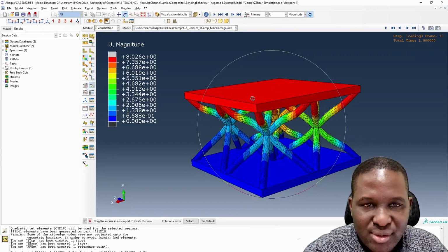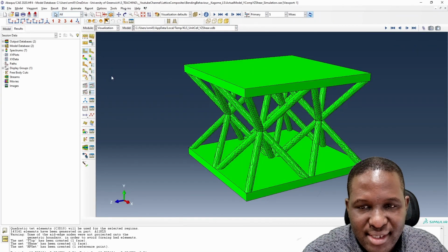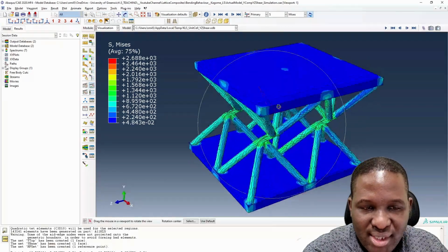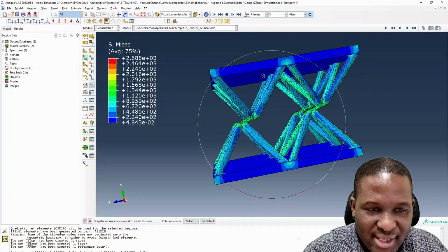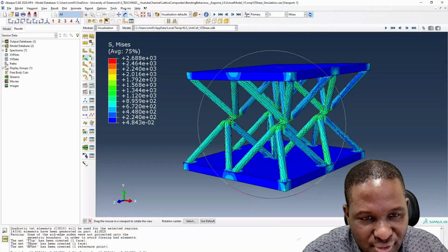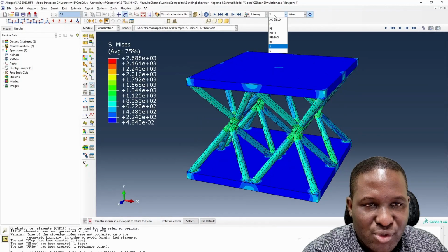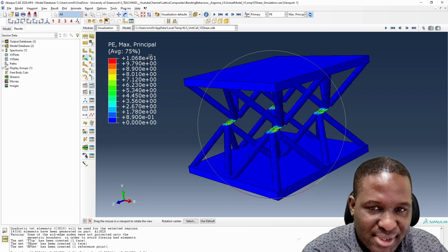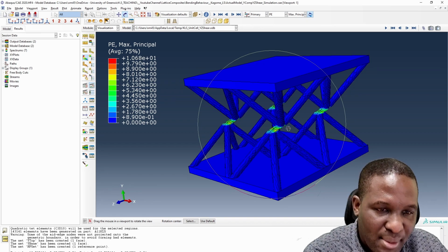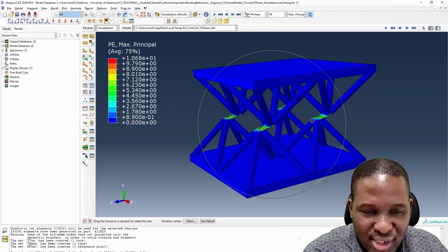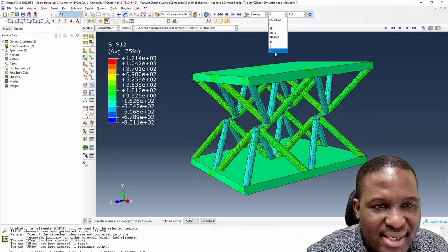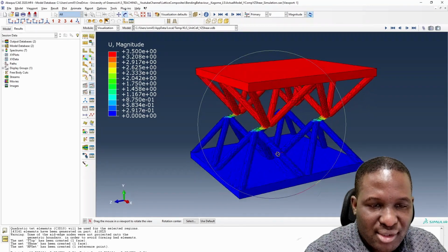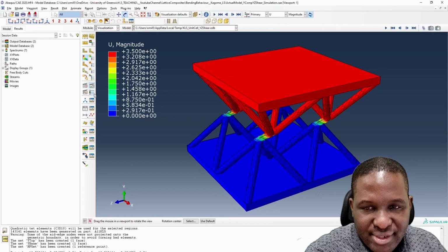So the next thing we need to do is to look at the shear case. So if we switch to the shear case, now you can see at the 30% shear strain that we've imposed on this model, it's shearing a lot, and right at the connectivity there, you get a lot of shear deformation building up in the structure. So if we switch to plastic strain, it tells you, okay, the structure has actually exceeded the strain that we specified. So there's quite a lot of strain, nearly 10% plastic strain. So this is why we're getting a localized failure in shear. So we can look at deformation. So clearly the top end is moving significantly due to the shear load, but the bottom is not moving a lot. And that's what you see in this simulation.